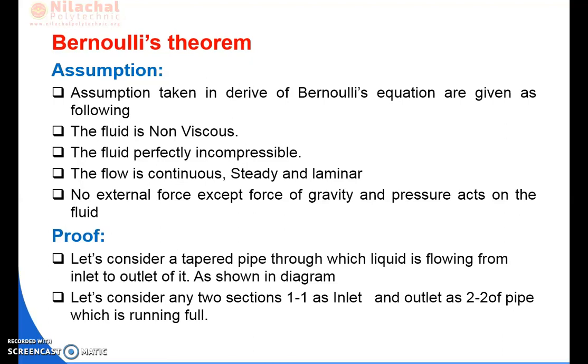Ideal fluid means the viscosity of the fluid is 0. Next one, the fluid is incompressible. At any cross section or at any section of pipe, the density of the fluid remains constant. The flow is continuous, steady and laminar.